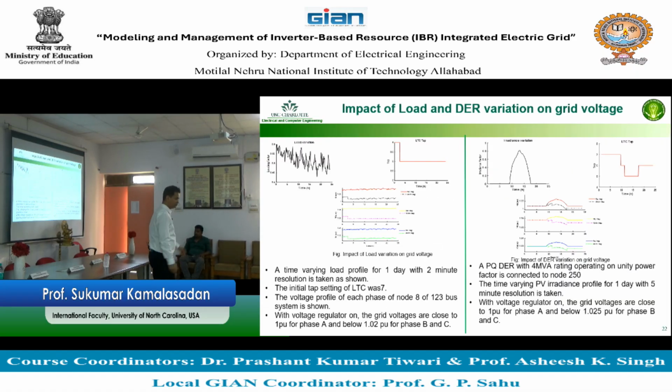So where it is used: if you look at a time varying load profile for a load, and you look at the initial tap for the LTC and the final tap for the LTC that is changing, the voltage profile of each phase of node 8 of the 123 bus, you can see this is with no regulator, this is with regulator.